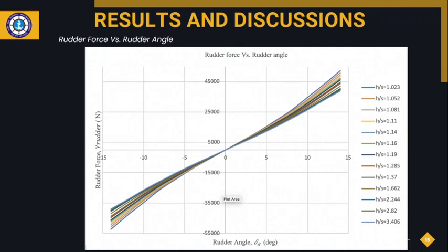So this is typically the rudder force versus the rudder angle graph, which is very similar to the straight line test simulations we do. And this is the plot which we use to extract Y delta from each case. So we see that the non-linearity has just built in.